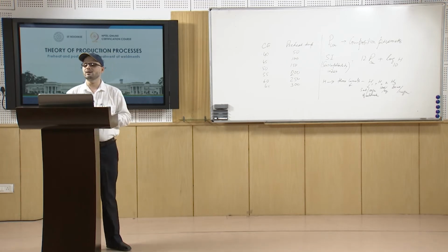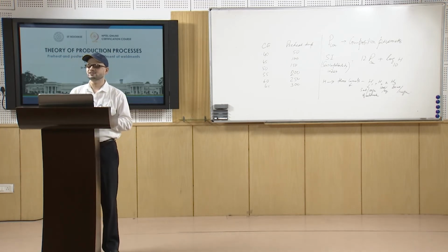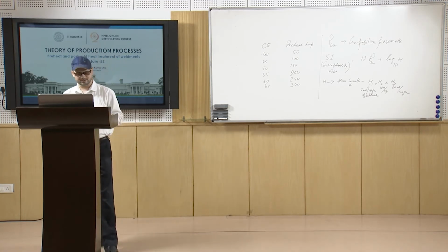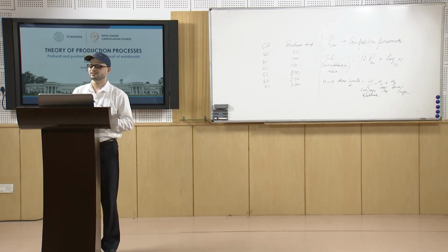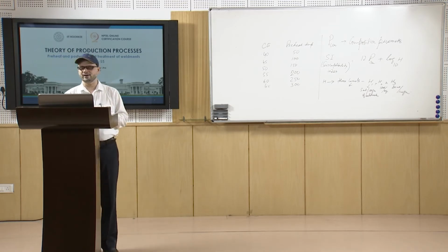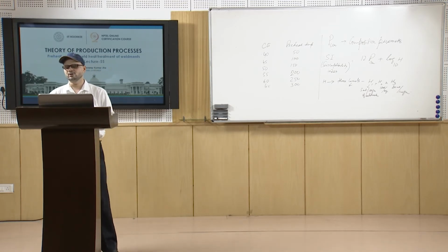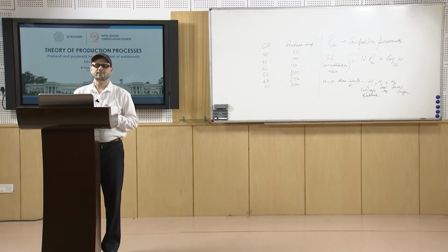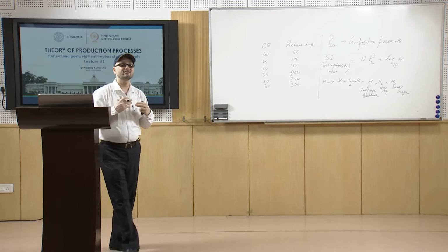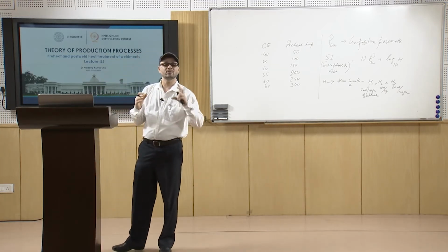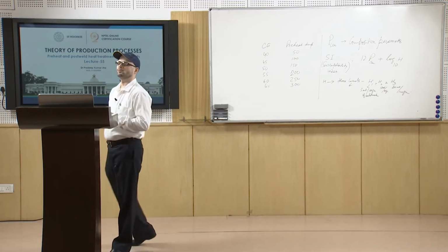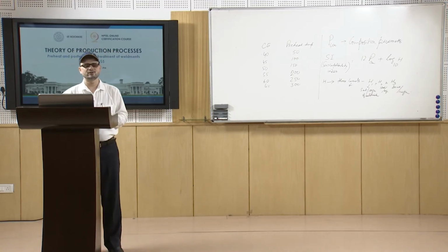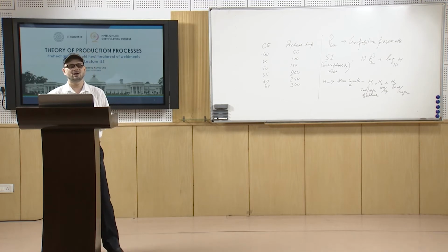Similarly, medium restraint is when it is attached to a structural network already. And when there is no movement at all, it is the completely high restraint type of weldment, and in those cases accordingly you will have to define the preheat temperature.